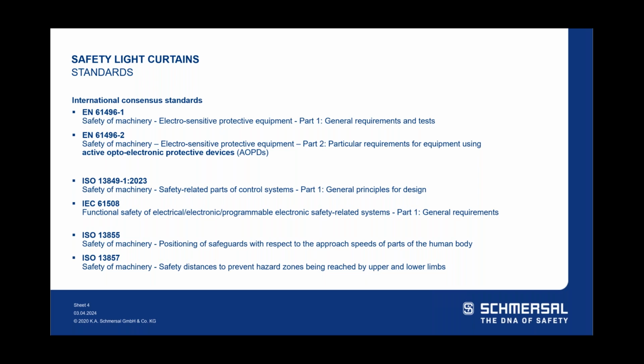We've grouped them together. So the EN 61496-1 and 2, safety of machinery, you can see it's all about electrosensitive protective equipment. Sometimes you'll see this as AOPDs. It's just another term for light curtains and like products, and it stands for active optoelectronic protective devices.